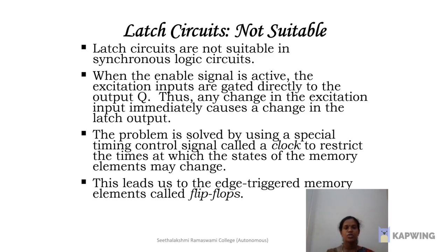Why are latches not suitable? Latch circuits are not suitable in synchronous logic circuits. When the enable signal is active, the excitation inputs are gated directly to the output. Thus, any change in the excitation input immediately causes a change in the latch output. The problem is solved by using a special timing control signal called a clock to restrict the time at which the states of the memory elements may change. This leads us to the edge-triggered memory elements called flip-flops.